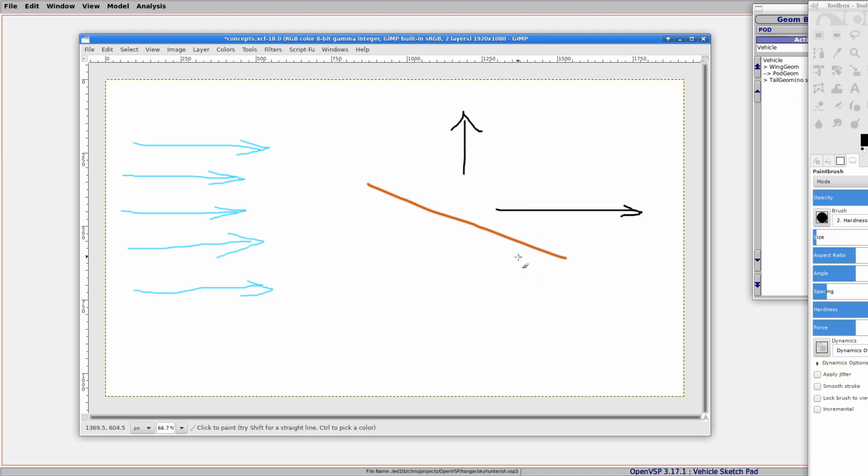So in some of the graphs that we're going to be looking at later, we'll look at something called the coefficient of lift and the coefficient of drag, which are dimensionless in that they're not measured in pounds or kilograms or anything. The only thing that's really important is the ratio between them. And we also have to consider that we have other forces here. So there's, well, weight, gravity, and then we have thrust going forward. But the thing about these two forces down here is they're a lot easier to adjust in the real world. For example, the weight we can adjust by using packing tape instead of fiberglass or something, and the thrust we can adjust by different type of motor, or 4S battery instead of a 3S battery or something like that. But these two here, they're a little bit harder to figure out, so that's why we're using a software package to help us with that.